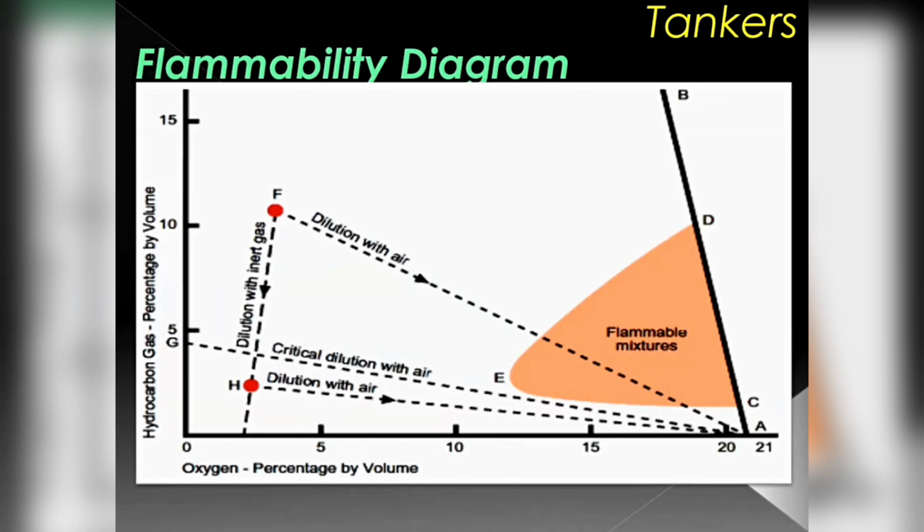That is the idea. If you have inert gas in the tank, as I said, introducing inert gas doesn't make a difference. It's not making the atmosphere safe as long as the oxygen percentage is not less than 11%. Very important. We cannot allow fresh air to go inside the tank. We are generating a dangerous atmosphere in the tank. That's why the inert gas system is required to generate less than 5% oxygen. Otherwise, it will not pass. It should be designed to deliver oxygen percentage less than 5%. So after the introduction of this, taking care of these two sides of the triangle, tankers have become safe ships. It's one of the safest ships now.